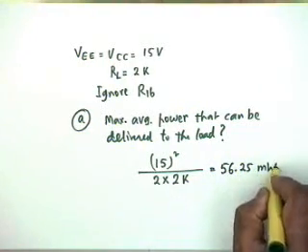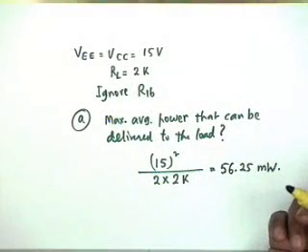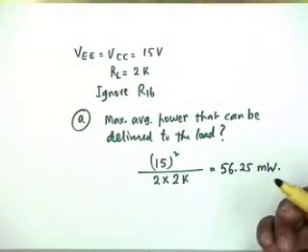This is the answer, simple answer. This has nothing to do with the complication of the circuit and things like that. All right? Okay. If you are fussy, instead of 15, you take 14.8. If you do not want to ignore that VCE sat, you take 14.8.